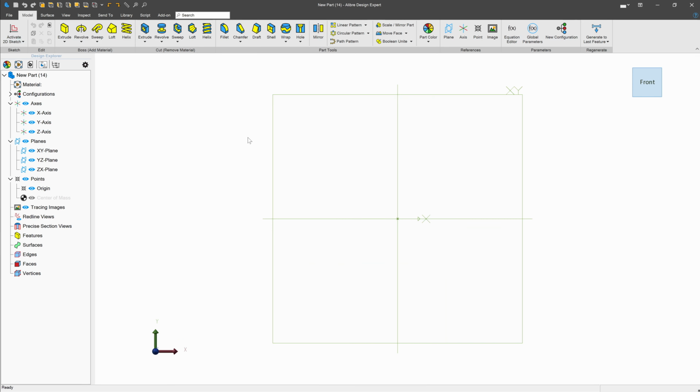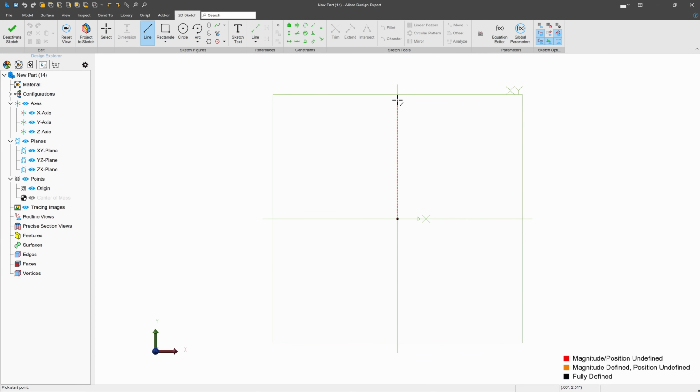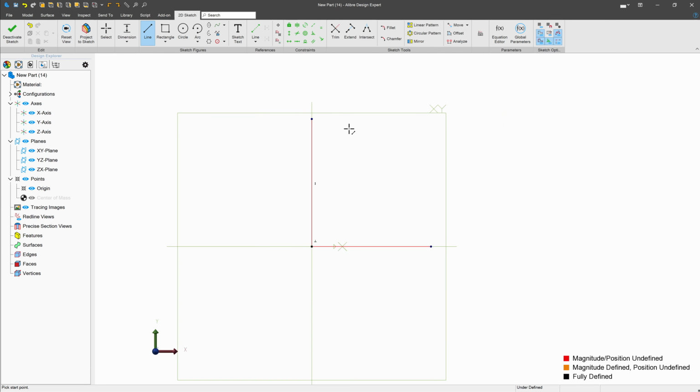So on this screen, I think I'm going to make a pawn, and I've always wanted to be good at chess. I don't think I am. So this is my little chance to maybe do something chess related and hopefully be good at it. So I'll start by making this nice L shape, and I can set some preliminary dimensions on my pawn. Perhaps I'll say 0.75 here, and I'll say 2.25 tall, and then I can make a circle. Right, this will be like the top curve of the pawn.